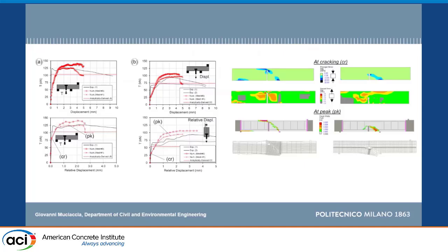Numerical models, also in terms of tension in the bar and displacement, work quite well. I have to say that they didn't work very well when the embedment is reduced, or we tend to a pure concrete cone failure, because after cracking, the stiffness is not sufficient. This is probably due to the fact that this is a rotating crack model. Probably with a fixed crack model in this case, you can capture the stiffness, but this also depends on the numerical result that you want.